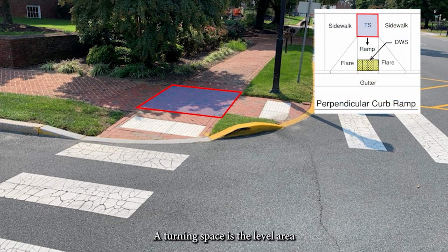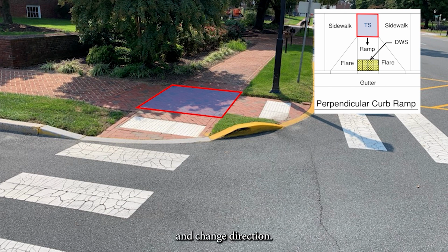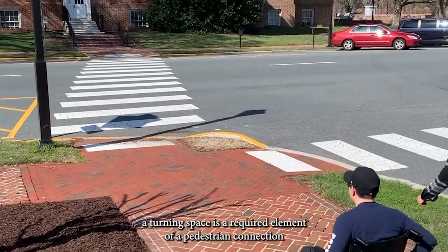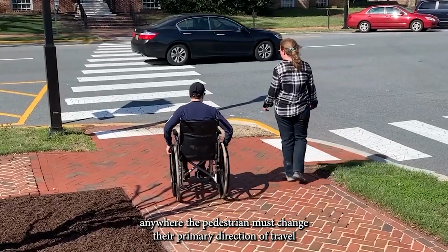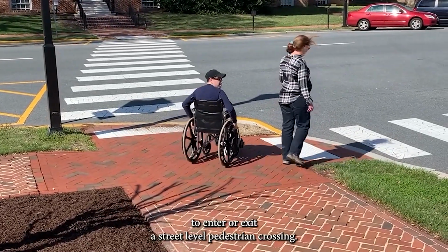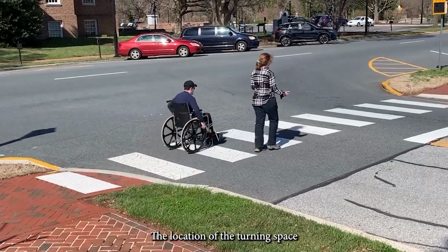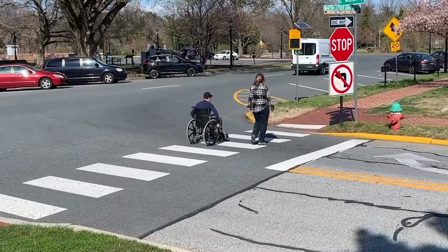A turning space is the level area beyond the ramped segment. The turning space allows for a user in a wheeled mobility device to maneuver and change direction. In fact, a turning space is a required element of a pedestrian connection anywhere the pedestrian must change their primary direction of travel to enter or exit a street-level pedestrian crossing. The location of the turning space is dependent upon the layout of the pedestrian connection.